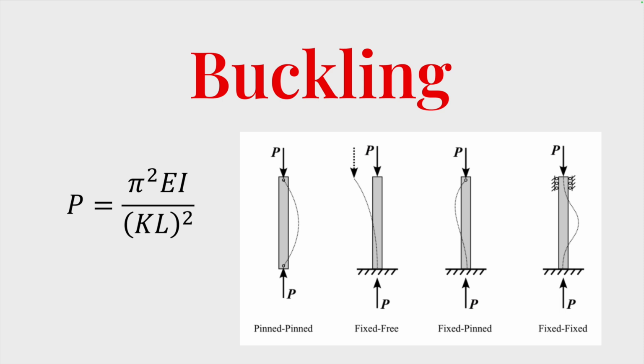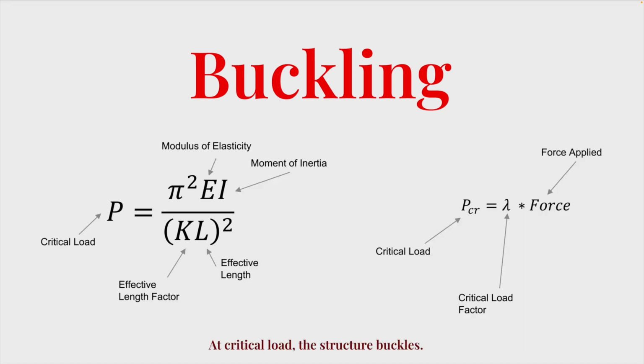Physically, buckling occurs when the potential energy of an external load is greater than the strain energy the structure can store by bending. Buckling is a bifurcation problem, meaning that there is more than one possible equilibrium state. At a certain load, the structure can either stay straight, which is unstable, or snap into a bent shape, which is stable. This study will find that tipping point.